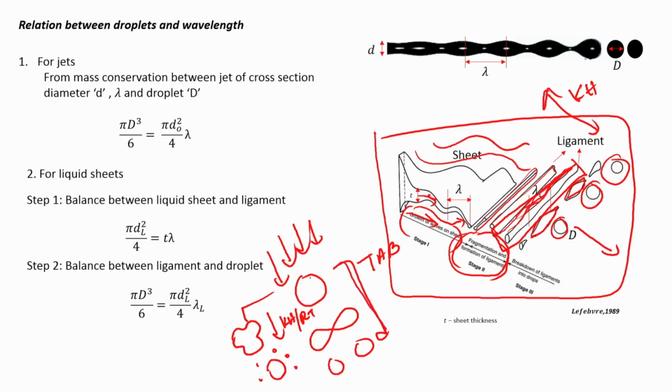It depends all on the droplet size, because your Weber number is proportional to the droplet size. So, if your droplet size is sufficiently low after the primary breakup stage, such that its Weber number is low, you can use the TAB model to predict the secondary breakup.